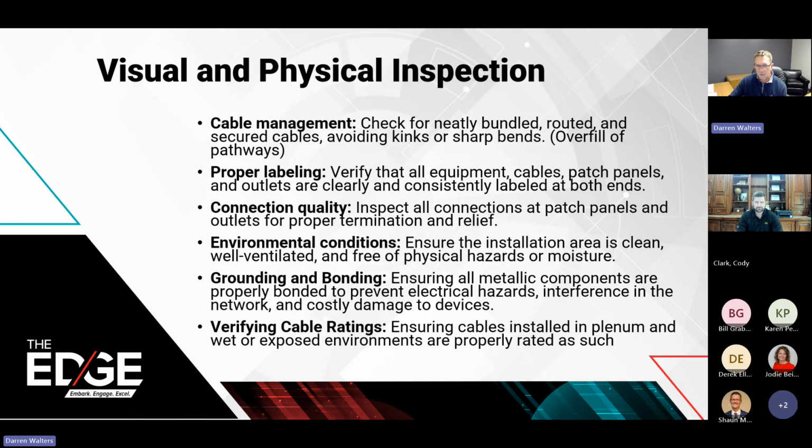And we get into situations with some of the older buildings, some stuff that we go back in and retrofit. We might run from the closet to a classroom or something, and we might be able to do 90% of it without having to break those plenum rules, but we've got one little chunk that we need to break it. So we don't want to run that risk, and so we install plenum for pretty much everything. It's just a touch bit more per box, but it saves us a lot on the back end. So that's kind of how we do it.